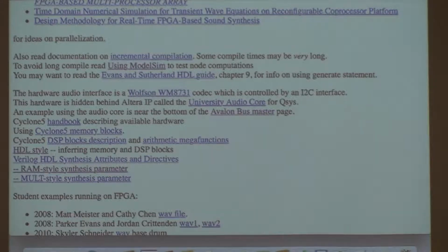Any questions on this? There's too many possible ways to do it. Choose one, stick with it. What I've done in the past is just use HDL style. I think it's slightly cleaner than putting synthesis directives in. I've used the HDL style method, which also works for multipliers.